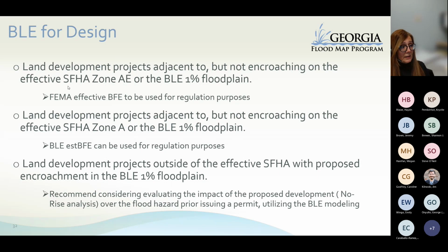So anywhere where we have a project which is adjacent to an effective special flood hazard area zone AE, the FEMA effective base flood elevations are going to be used for regulation purposes. So they're still regulatory and they're still going to apply.